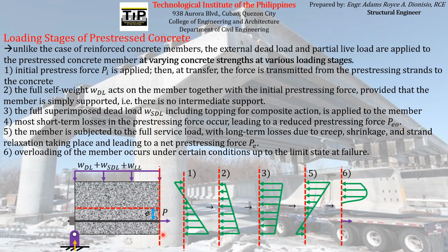If the cracks have already propagated to the upper portion of the concrete, it means the tensile stresses acting on that part of the cross section have already exceeded the maximum tensile stress that can be experienced by the concrete element itself. But because of the existence of steel reinforcements as well as the pre-stressing reinforcement, the tensile stress that is supposedly carried by the concrete element will now be transferred to the steel reinforcement and the pre-stressing reinforcement themselves.